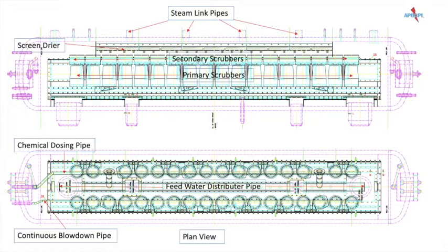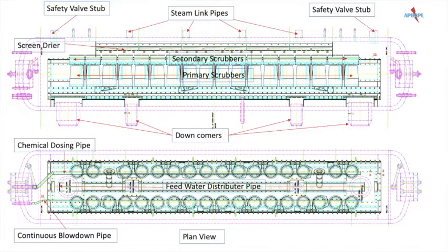The steam drum also has downcomers for supplying subcooled water to the heat-absorbing tubes, safety valves for high-pressure protection, instrument and water level tap-offs for various control instruments like the pressure measurement, drum water level instruments etc., and an intermittent blowdown pipe to blow down water in case of any sudden upsurge of steam drum water level.